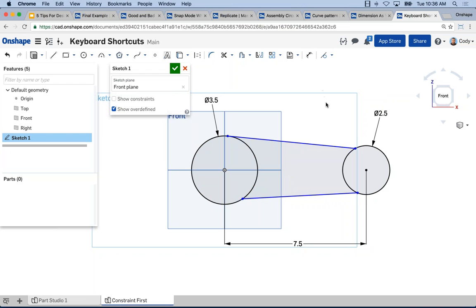It's nothing wrong with this approach, I should say. But again, line, circle, tangent, right? And you can see line, circle, tangent. Now the icon does change, which is helpful. I don't have to go back through the dropdown, but you can see I'm doing this 4 different times: line, circle, command, line, circle, command. And so that workflow of geometry, geometry, constraint, geometry, geometry, constraint. We've all done it, and you have to do it a lot. But there is an opportunity to save some time here.